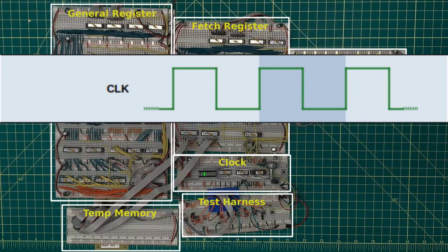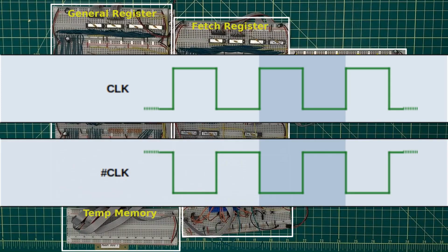So here we've got the clock signal. Obviously, this is going to be generated by my clock circuitry. I need to invert that clock as well. What I really need to be able to demonstrate is that those two signals are as symmetric as possible. I want to have almost no delay, and if I can get absolutely zero delay in that clock cycle versus the inverted clock cycle, that's going to be ideal. What I want to be able to do is manufacture the delays I need in the actual control signals themselves and not have to rely on an inverter to provide a delay to an inverted clock signal.